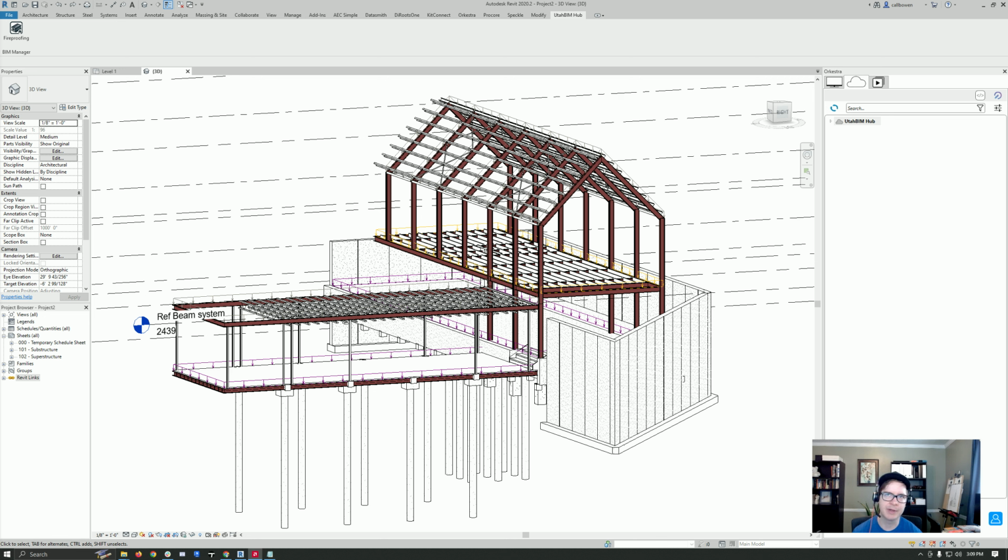This week I'm going to be showing off our steel fireproofing Dynamo script that lets you select structural steel elements from a linked model and create fireproofing around them with the thickness that you need. This is super helpful in clash detection to have the fireproofing model elements showing up for each steel piece. It helps all of the people coordinating with you see them in the coordination model, or if they bring them into Revit through a linked Revit model, they can see them too.